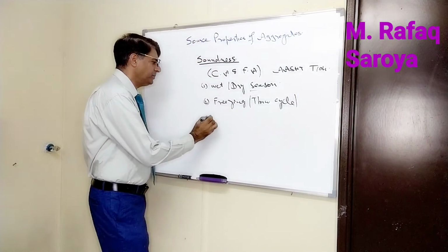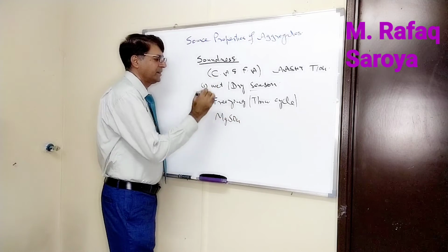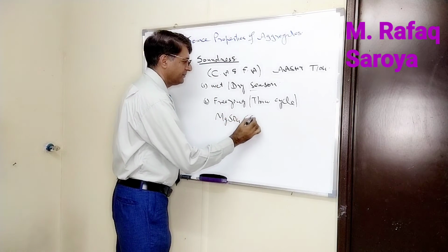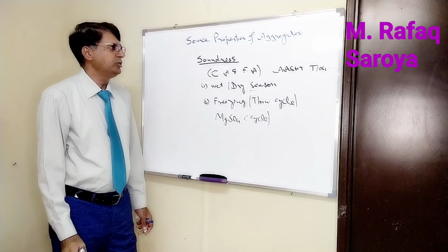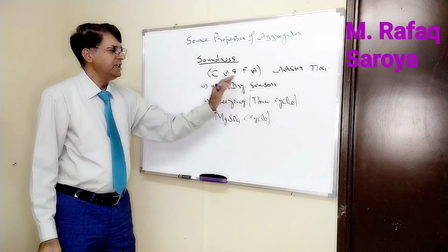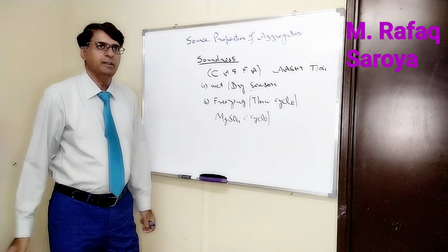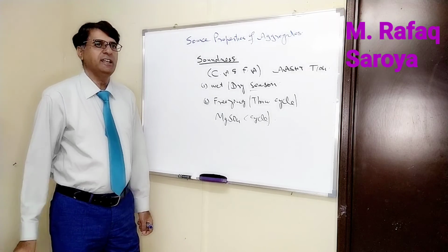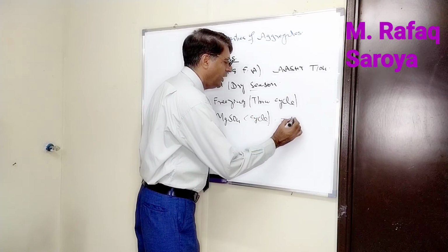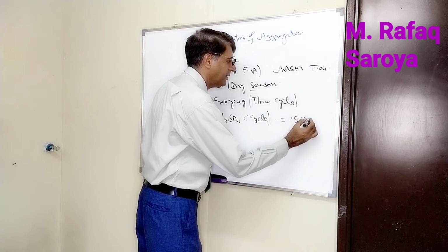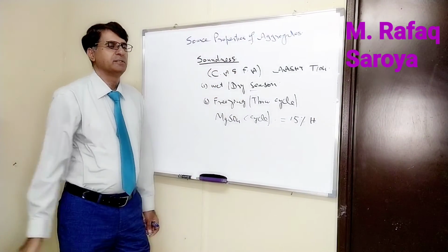Here we are going to use magnesium sulfate cycles in order to check this cyclic condition, and there we will see how much disintegration is going to happen after certain cycles, and its maximum allowable is 15% for heavy traffic. So you will have to check it.